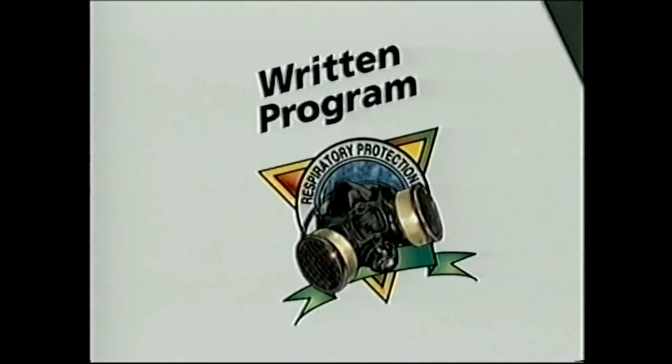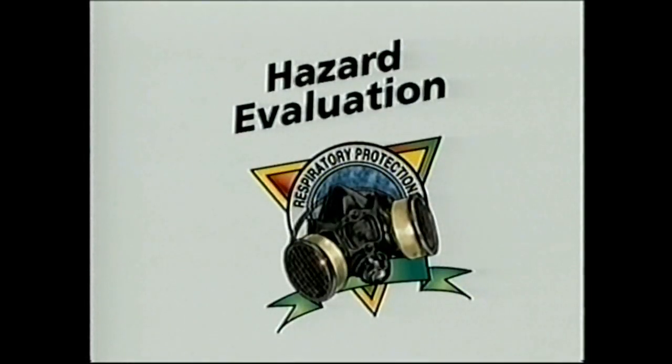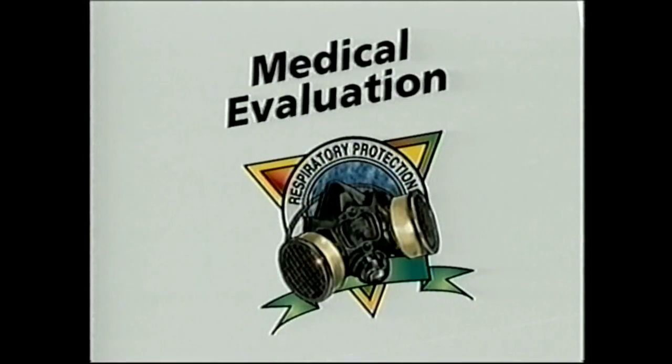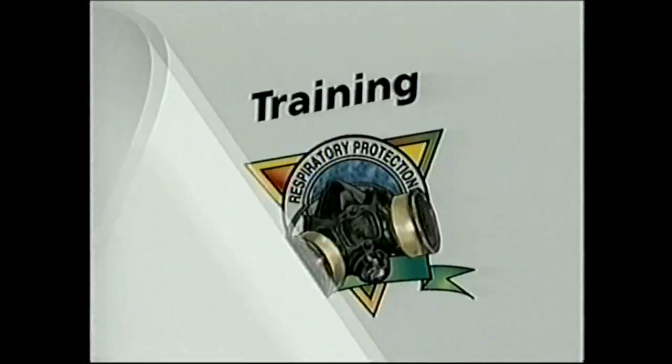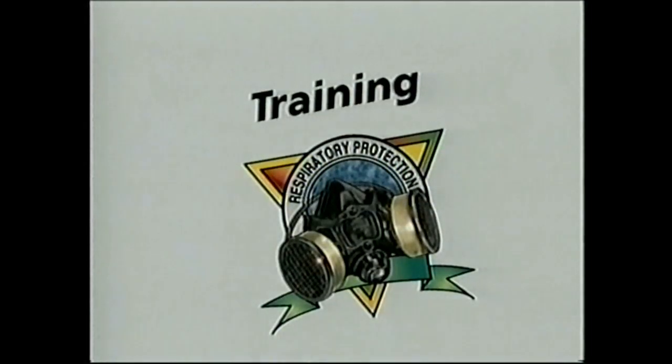Wherever employees are required to wear respirators on the job, employers must develop a complete respiratory protection program. This consists of a written respiratory protection program, a hazard evaluation, a medical evaluation to determine if workers are physically able to wear a respirator, fit testing of respirator face pieces for each employee who is required to wear one, and proper training. As part of this training, for the next few minutes, we'll be looking at the different kinds of respirators you may need to protect you from the hazards and contaminants in your workplace.